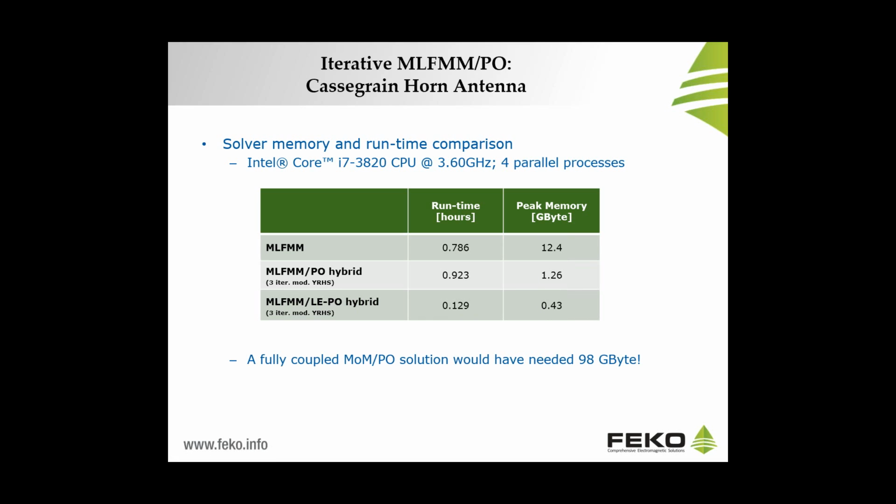And the other thing that I would like to point out here is that if you would like to use the fully coupled method of moments with PO here, you would need 98 gigabytes of memory, and this shows the big difference between the new methods and the method just using method of moments and PO.